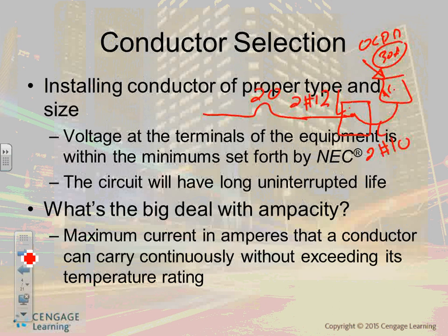They could have made it run at 240, and then you'd need only two wires. But I'm sure they have their own reasons. Every appliance is made differently. So they think the best way to do it is to run one at 120 and the other at 240. Now, you as an electrician or electrical designer need to know that. If you don't know, you need to ask and then provide the neutral or not.